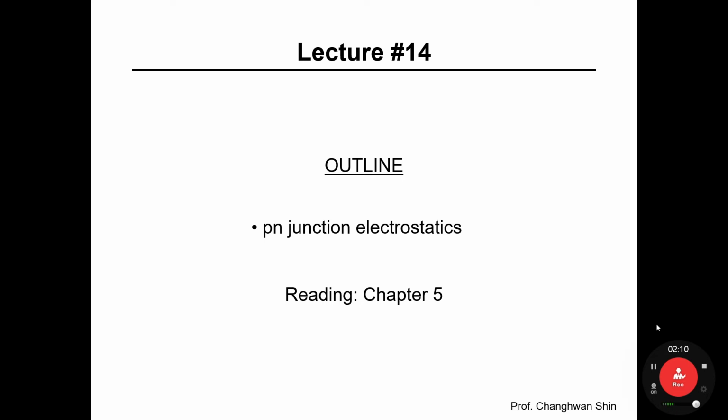As I told you when we learned MS contact, electrostatics means we should understand how four major parameters, such as charge density, electric field, potential or voltage, and the electron's energy in the MS contact, are closely associated to each other.